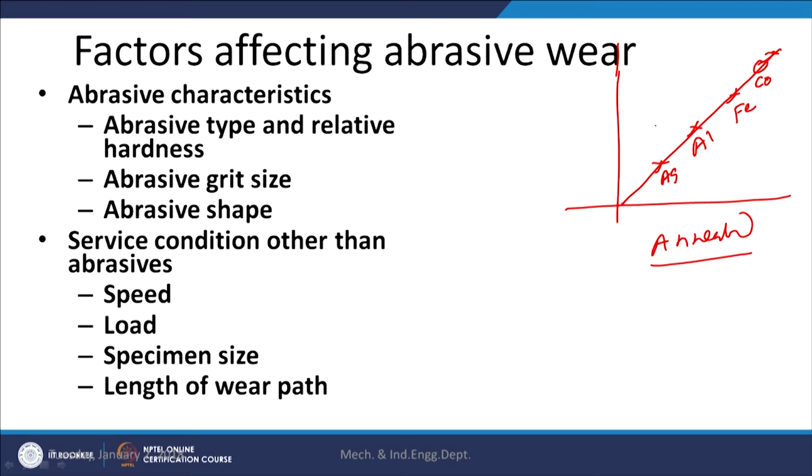So, the material hardness in annealed condition, and what it will be showing is increasing wear resistance. In annealed condition, it will not have any work hardening effect, and the flow stress will be the same as the yield strength of the material.